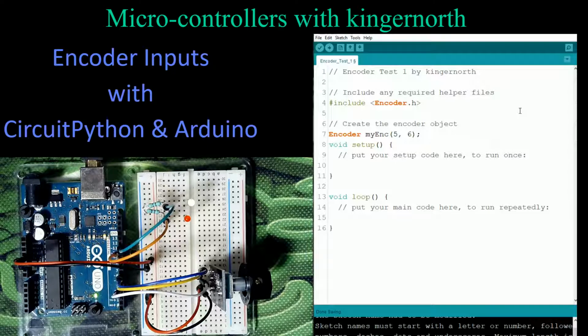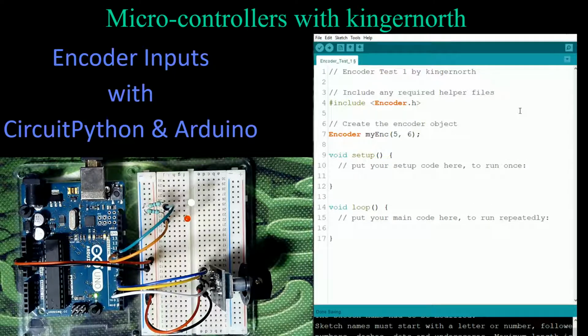Now, you have a choice of pins here. These are just standard inputs, so they'll work fine. Something on the Arduino boards, like this one here, is pins 2 and 3 are referred to as interrupts. This helper file will allow you to use interrupts, which will give you faster reaction when you're turning the knob. So if you have a big program, you don't want to miss when you're turning the knob. And think about it as turning the volume control on your car radio. Usually a lot of your cars now, they have volume controls, and you turn the dial and it turns forever. And that's because it's an encoder. So you could do something very similar with this. You can do it to dim and brighten lights by turning a knob and have multiple turns to make it happen. There's no stops at the end of it.